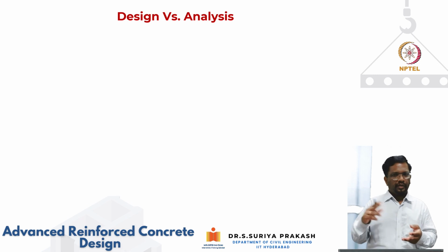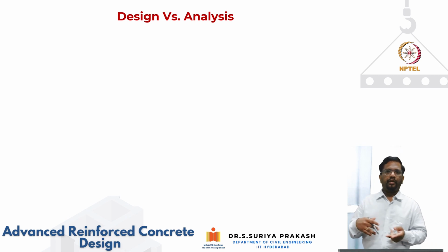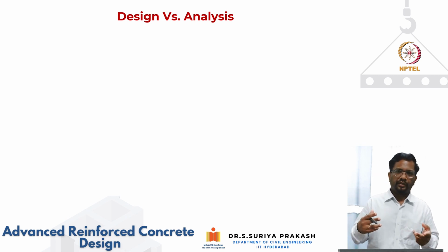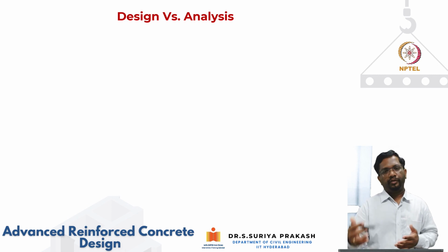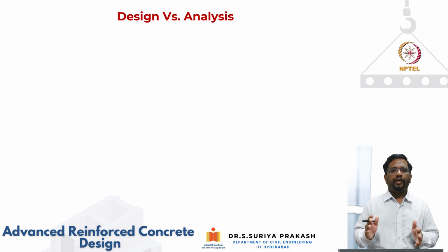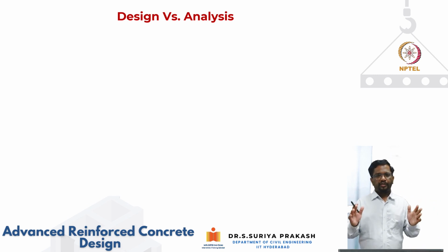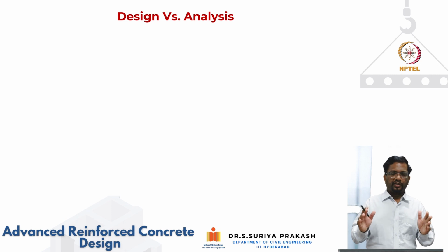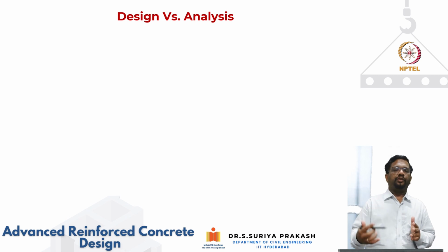These are the three types of design that we usually encounter in concrete systems. One is plain concrete design, typically used for non-structural systems, then reinforced concrete design used for regular designs, and then pre-stressed concrete design depending upon your requirements. Pre-stressed concrete is also going to give you more durability because under service loads we are going to have mostly crack-free conditions. Again, in pre-stress we have type 1, type 2, type 3 design. Let's not get into that, but usually pre-stressing is designed in such a way that under service load these elements are not going to be cracked, so the durability is also going to be higher.